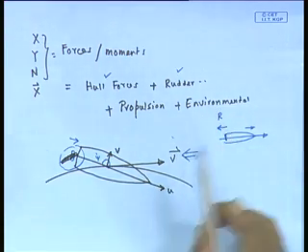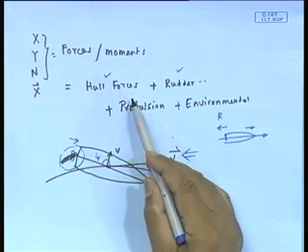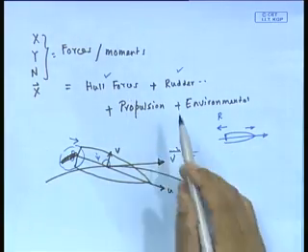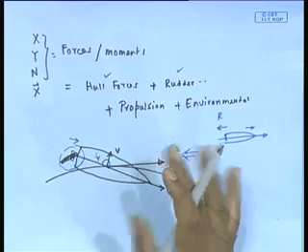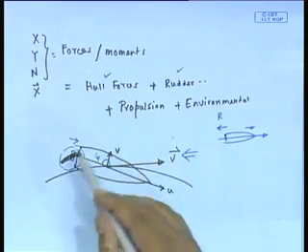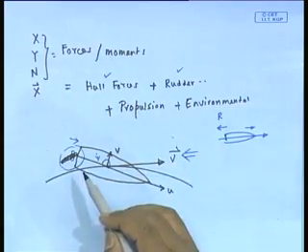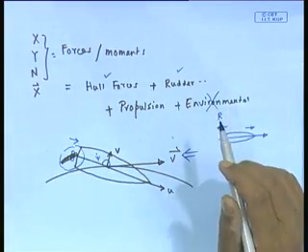Now, we are going to consider only the hull forces. Why? Because consider this case. I want to investigate first, before the control surface, the straight line stability. Remember, my hull was going on a straight line and I just caused it to turn by a small angle, to disturb the hull. No environment because it is calm water, just like resistance, I presume the study is in calm water. So, this I remove.